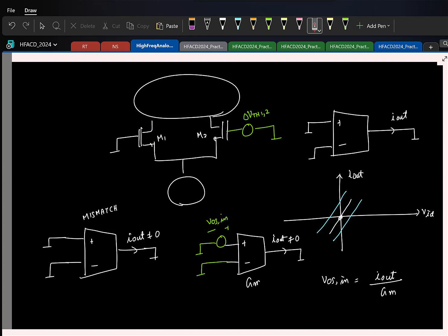Again, the argument is the same. Assume that these are the only mismatched transistors. We are going to model the offset by an equivalent voltage source at the input. Now, to model the mismatch of these two transistors, you are using a voltage source at the input. That's going to be the same. So just like noise, the threshold voltage mismatch due to the input transistors is going to directly appear in your input referred offset expression. And usually this threshold voltage mismatch is what is dominant, so we will not consider current factor mismatch at all.